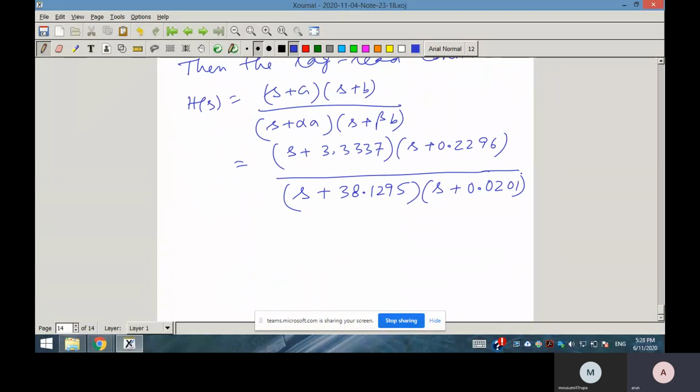Okay, so you can see that the lag controller is acting like almost a pure integrator, into a PI type of controller here. Because for the lag controller, the main objective is to provide phase attenuation, and the phase lag that is provided by the lag controller is assumed to be negligible. There's only 2 dB here.